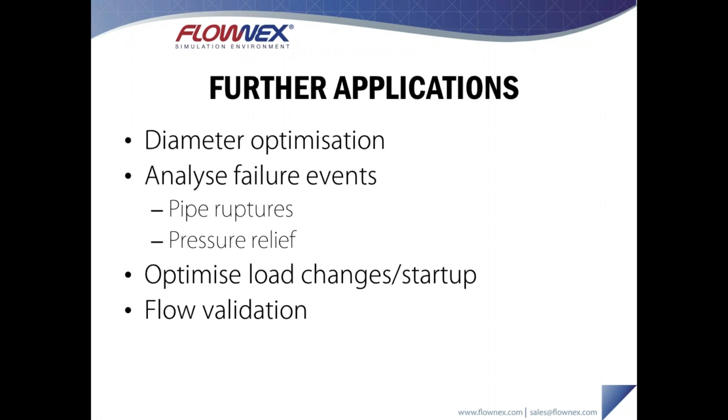If our pump is specified with an electrical efficiency as well, we can actually get the electricity or the power required to run that pump. And using the diameter and this operating power, we can start developing basically an objective function for the total life cycle cost or the total lifetime cost of this particular pump and pipe arrangement. We can then perhaps use a sensitivity analysis or the optimization feature and look to minimize that cost over time and select the most appropriate size piping for our system.